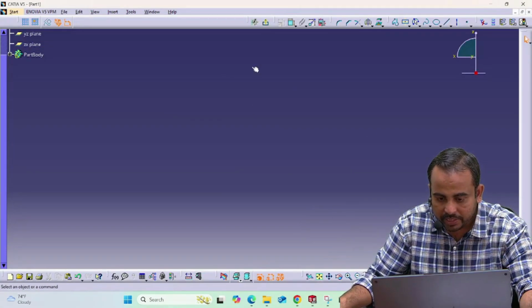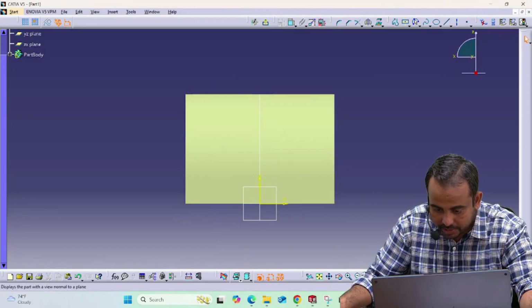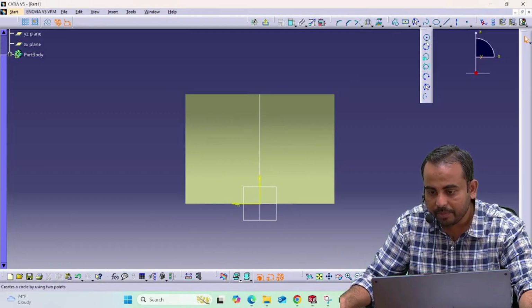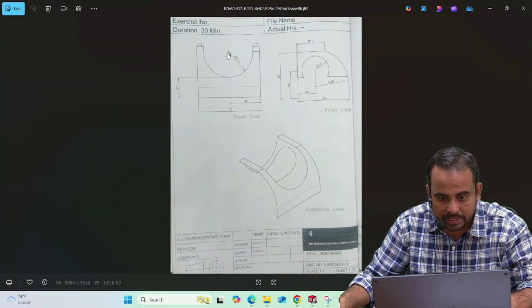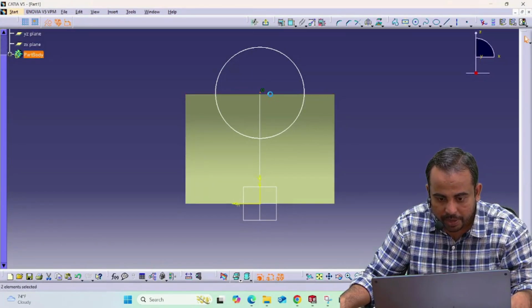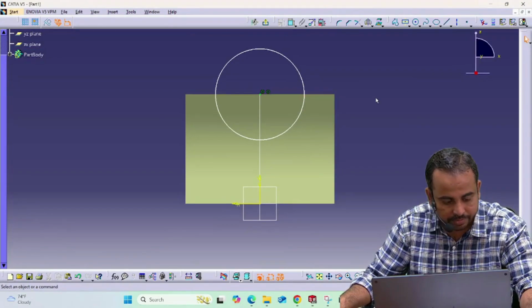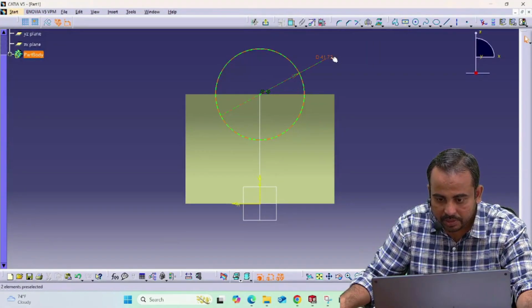Now for center fitting of the sketch we are going to click on this icon that is in view toolbar, command known as fit all in. If I want to flip the part orientation, you just need to click on this option, that is normal view. Again go for circle command now. Here the circle center is given collinear with these two edges. So we are going to take this point on this edge, say the relation as coincide for proper positioning. Next the radius, that is 27.5.